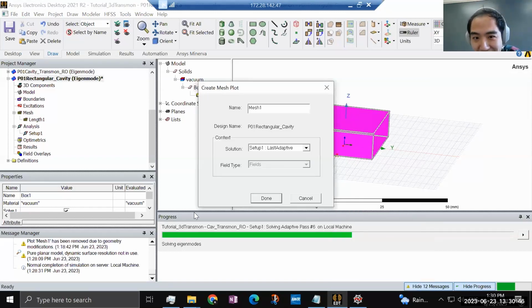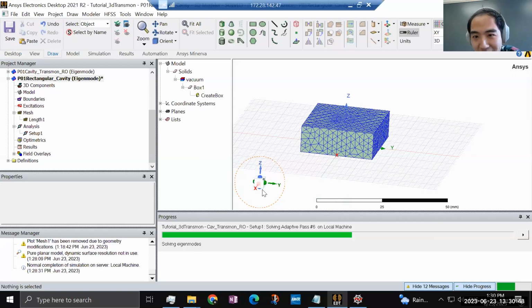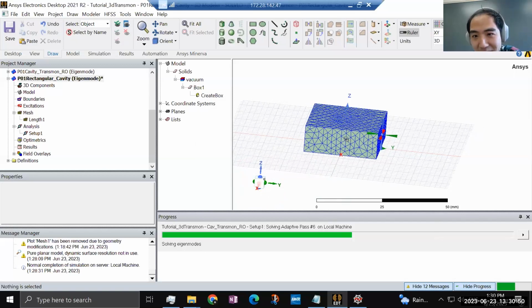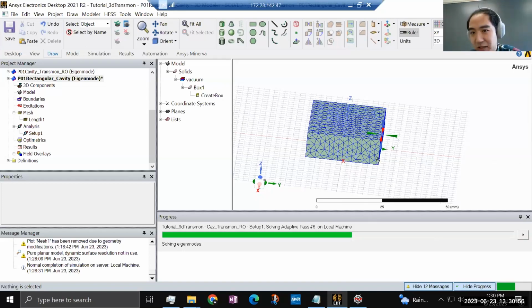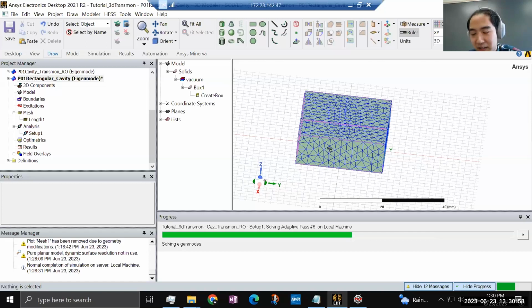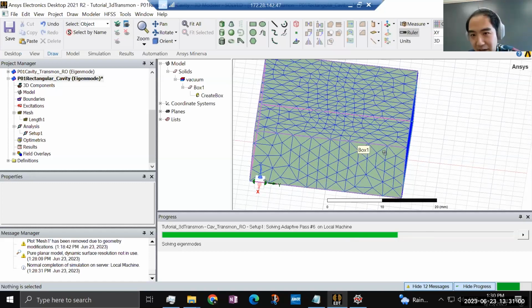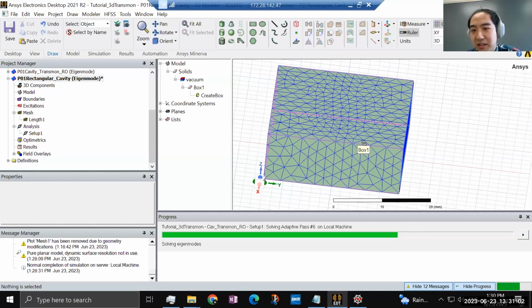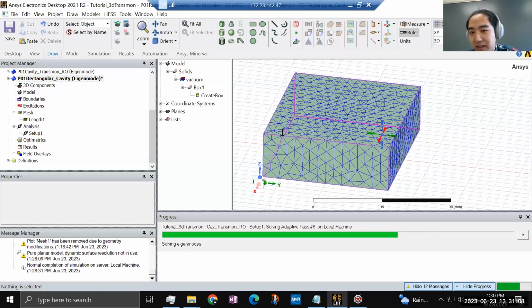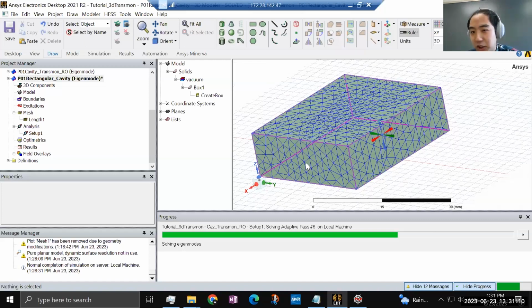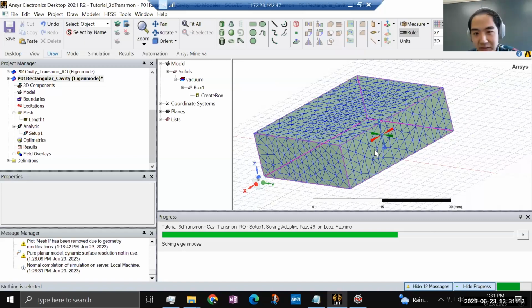For this example, it's just a box mode cavity. So I know exactly what the mode should be, and I think just meshing like this should be able to capture the eigenmodes of this box very faithfully. So I ask it to start with no larger than 4 millimeter in the mesh size, and this is the mesh it converges to.